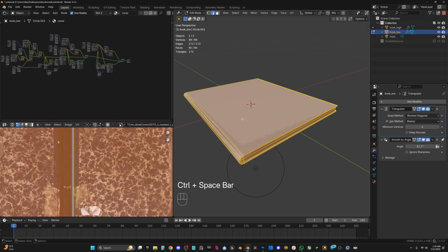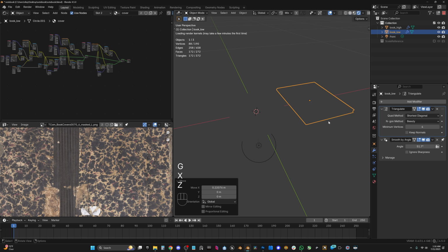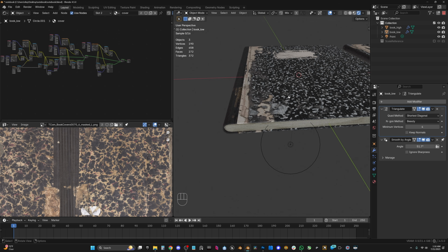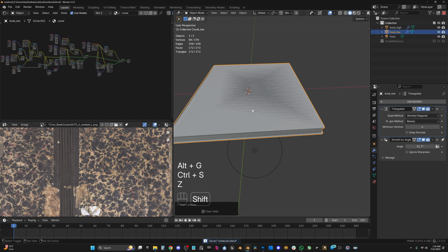We haven't really changed things, but you do want to make sure your low poly has UVs. A few things to take note here. Because we lost that loop, we lost that material assignment that we needed with the high poly. So we're going to have to do a high to low bake, which is exactly what I wanted to show you. Save everything, go to object mode.